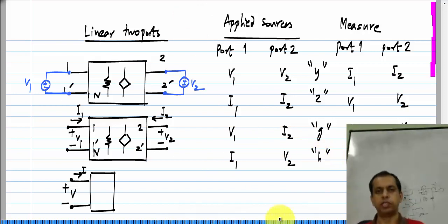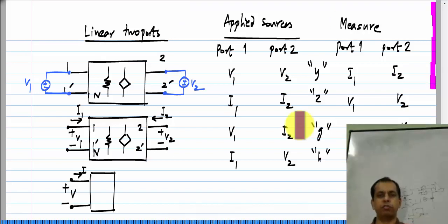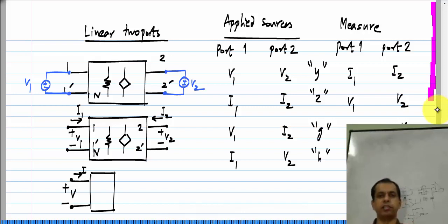Okay. So, these are possible 2 port parameter sets, and all of them are equivalent. Now, like before, for some circuits only some of them could be defined and the others could be undefined, but if you have a circuit for which all of them are defined, then all are equivalent descriptions. Which one you choose is based purely on convenience. Okay. And this is just like sometimes in calculations you would use conductances instead of resistances, or you would use Thevenin equivalents instead of Norton equivalents, and so on.